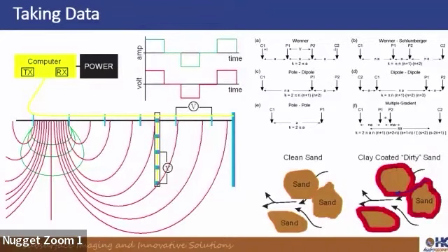And this is how we make our measurements. We have a computer that controls the transmitter, which passes electrical current across metal objects in the ground. We use stainless steel stakes, and they're usually aligned at even intervals. We can use electrodes in boreholes. We can use just big pieces of metal. This is a well, for example.